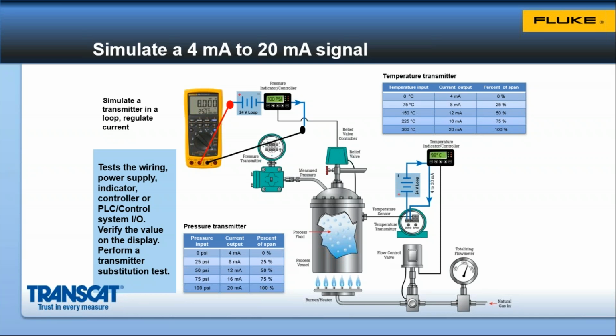And if the problem goes away, you would know then the troubleshooting that you need to perform is either going to be that particular process transmitter, or perhaps the input to the process is clogged, or the process sensor is intermittent or defective. But it's a very powerful test, and is used more often than milliamp source because of the value in performing the test and all the things it tests in that control loop.